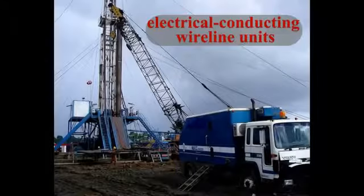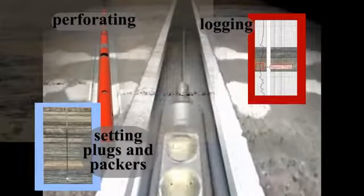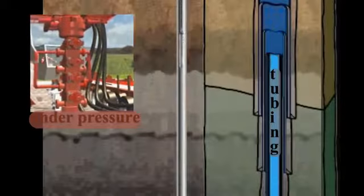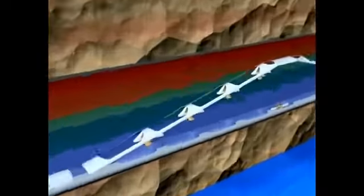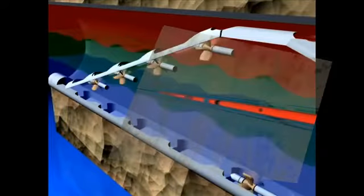Electrical conducting wireline units. As this illustration shows, this multi-strand electrical conducting wire is used for logging, perforating, and setting plugs and packers. It is run both through tubing, under pressure, and through casing when the well is killed or taken off production. This procedure is used to run production logs, which can help determine fluid flow rates and gauge the current effectiveness of perforations.